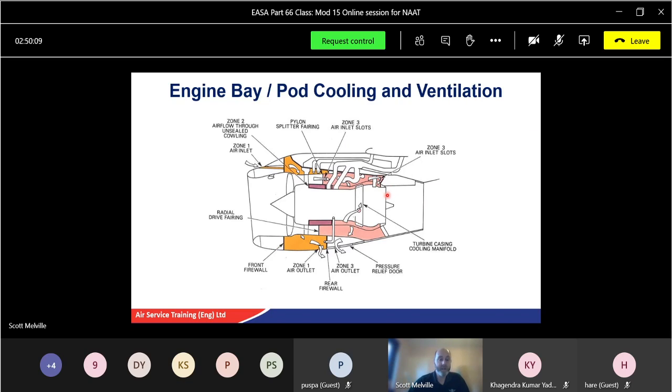Well, that's already on fire, but yes, that could escape. But there's a good chance of a mechanical hot fire where all the electricals are, the fuel pumps, the hydraulic pumps, etc. So zone 1 is the forward one, and it's the most likely area for a fire to start, and therefore it's fitted with the fire detection and remotely operated fire extinguishers.